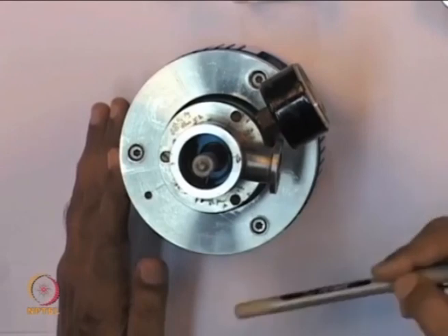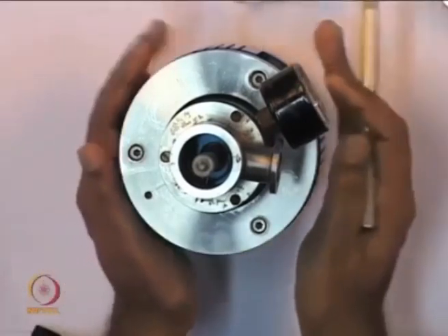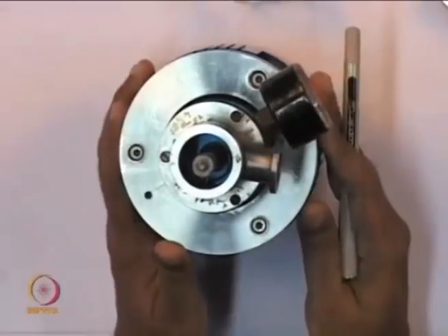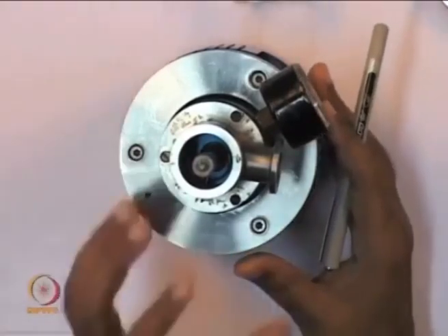If I want to carry out a very efficient design of this cryocooler, my power input to the compressor should be as minimum as possible, so that the coefficient of performance, or COP, is very, very high. So, the whole design analysis has to be carried out to predict the performance of this cryocooler, and then one has to devise the dimensions, fabricate it accordingly, and see the experimental results. In this way, we do Stirling cycle cryocoolers, GM or Gifford-McMahon cryocoolers, pulse tube cryocoolers, and things like that. These are the various types of cryocoolers one can design.